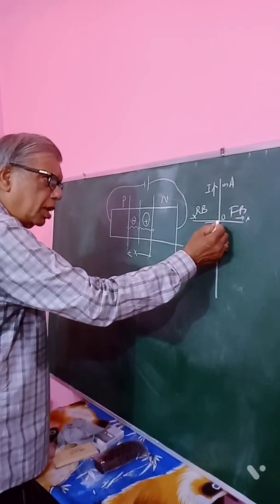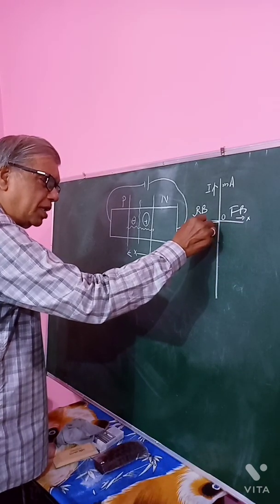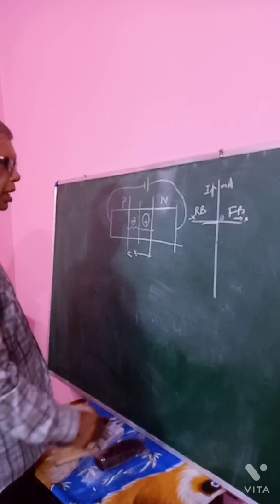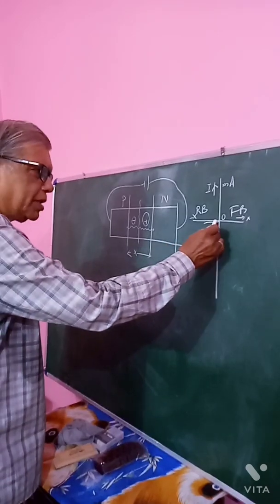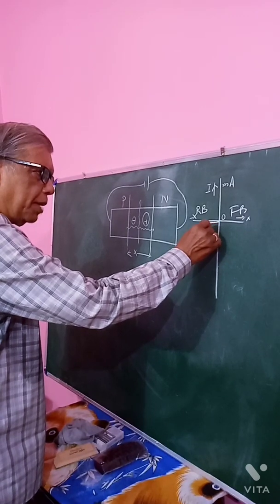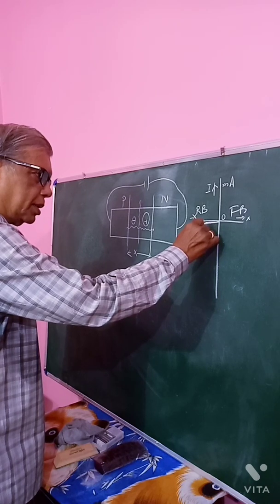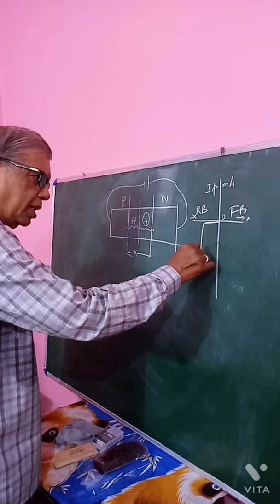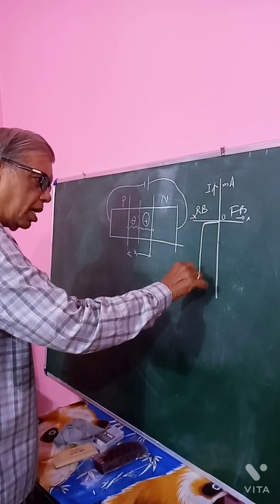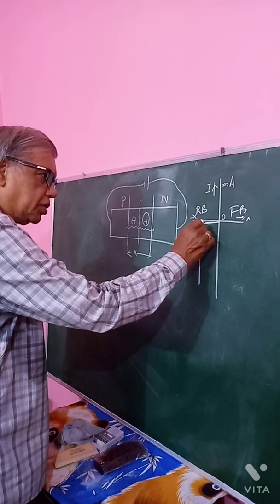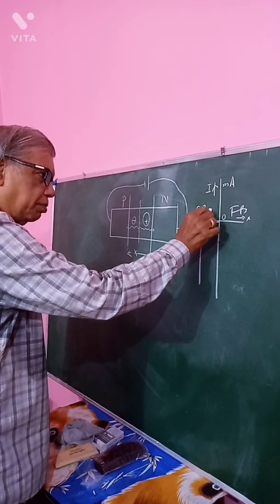This is how the current varies with potential, a very small variation. Now for Zener diode, this variation occurs till a potential is reached where the current increases very sharply, and this voltage is called Zener breakdown voltage, or Vz.